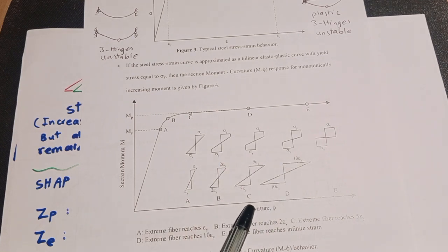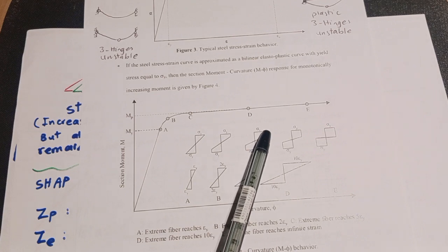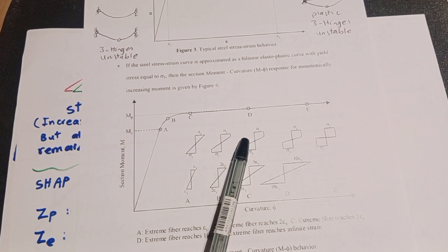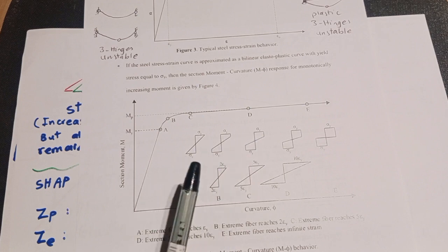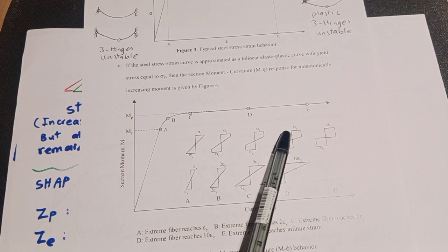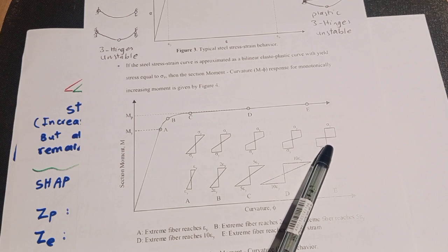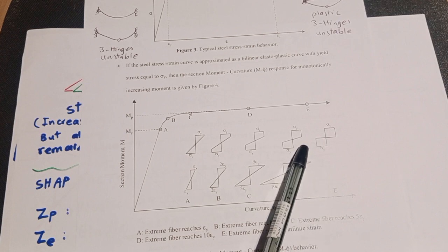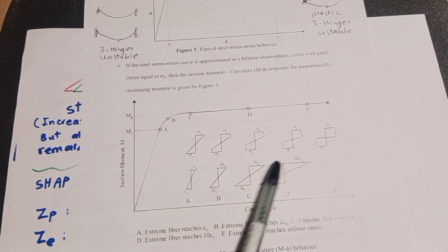And the same for point C, strain is still increasing linearly, and stress is reaching Fy in the next layers until covering the whole section around the neutral point. And the same for point D, the whole section is still experiencing increased strain, but the stress is going to cover the section fully at Fy. And finally at point E, the section has collapsed and can't take any bending moment. We call it the collapse point, and the whole section is under Fy.